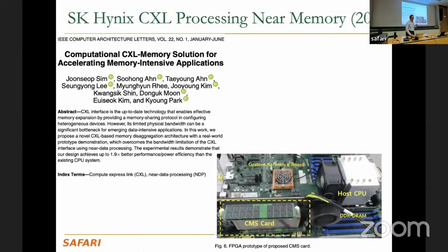And more recently, people have been proposing interconnects that are more flexible. When you go off chip, a flexible interconnect can enable abstractions such that you can offload computation to some other component in the system, some other device. It could be storage, it could be memory. CXL, or Compute Express Link, based interconnects enable that.